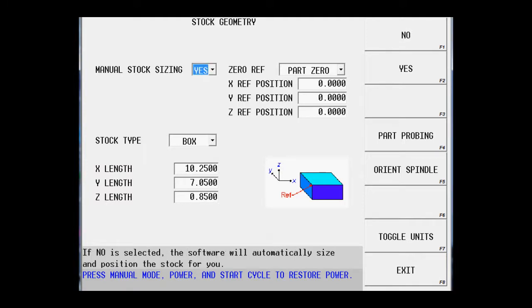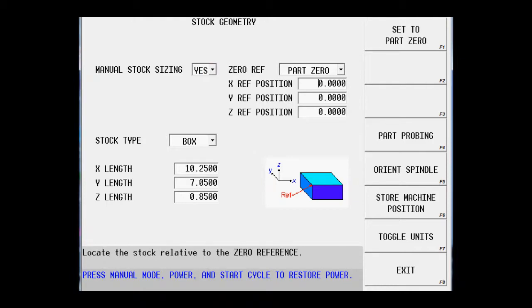Now we notice the center of the large radius is 0, and we have some values here in the bottom left corner for X and Y to move our stock into position. So we're going to put those values in. We have a minus 4.3374, and a minus 3.5179 for the Y, and that should bring our stock into position, making the center of that large radius our 0.